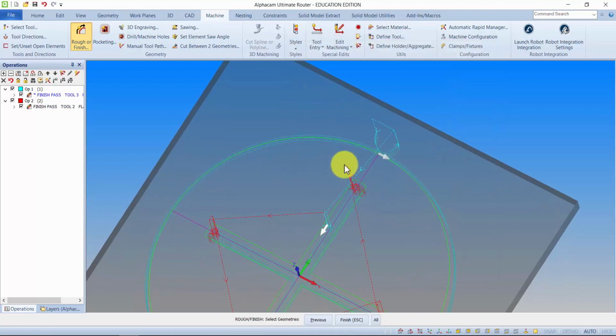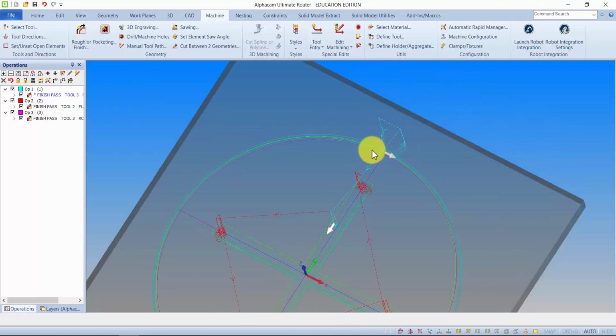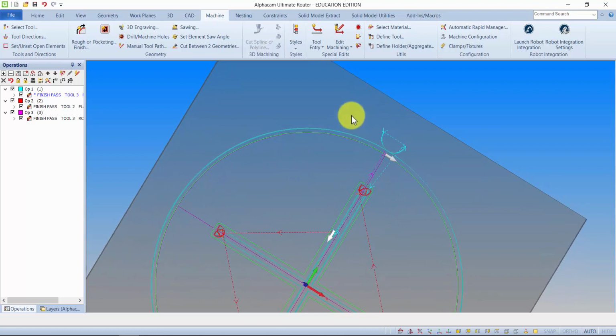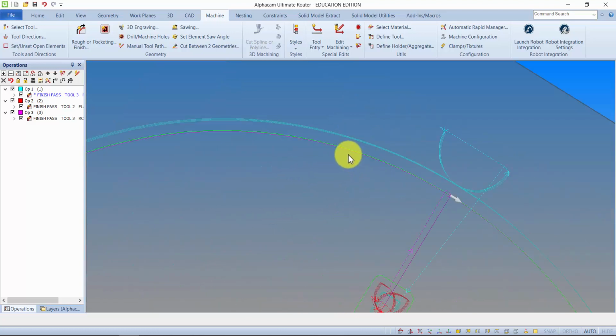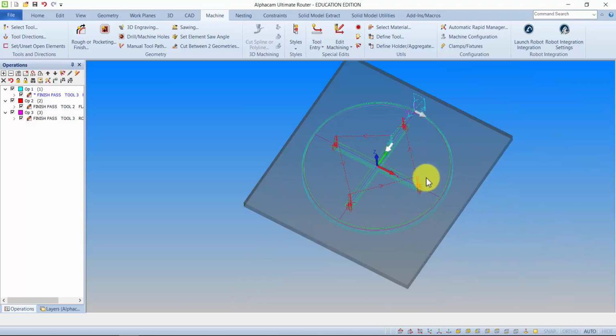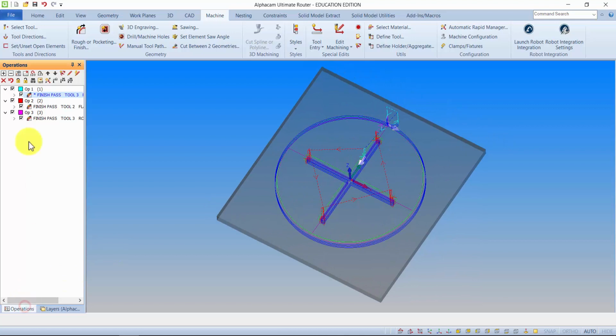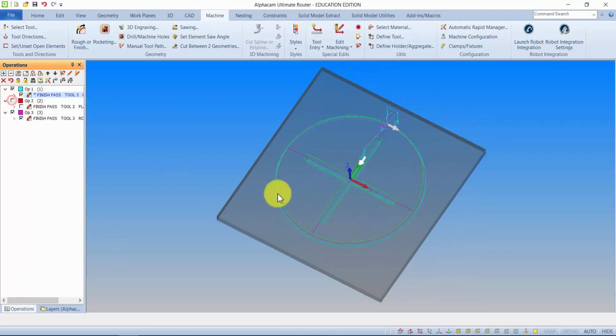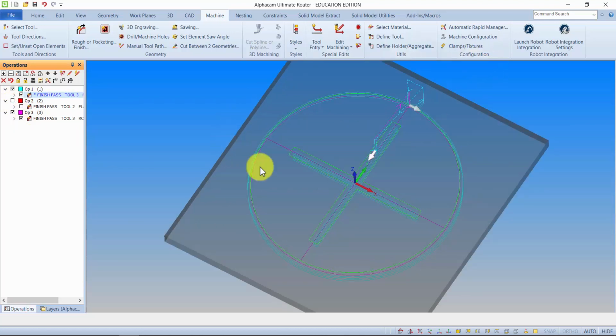select this green circle. So if you press Finish, you'll see another toolpath, another purple toolpath in this case applies itself. And because this V-groove cutter needs to run on the center of that line, that's why I brought the ghost tool in there. And to speed up the simulation, I'm going to go to my Operations tab and temporarily turn off the red operation, and that'll just speed it up a little.